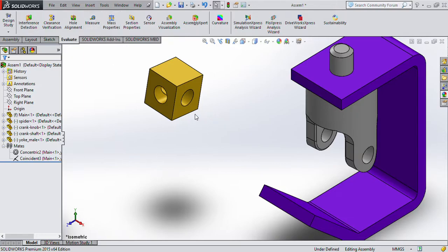One possible way is to go back to part design and control the sketches, but this one is very time consuming. Much better to use evaluate here. Now I'm going to use evaluate and measure. Now if you select this circle, it will represent us, the diameter of this circle is 9.53.